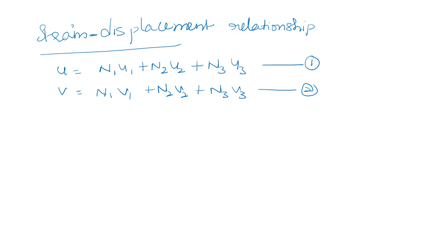Now the strain, which is the ratio of displacement to length. So the normal strain in x direction, in two-dimensional cases, we have an idea. Strain in x direction, normal strain. These equations we already discussed in the first unit. At the same time, we would be knowing them from mechanics of solids also. Strain is equal to what is the formula? Dou u by dou x. Normal strain in x direction, dou u by dou x.